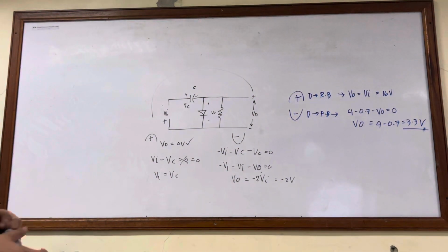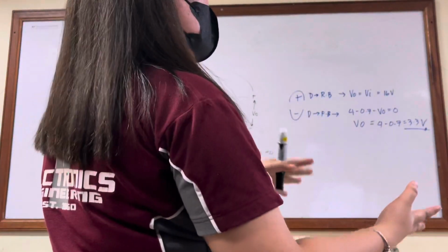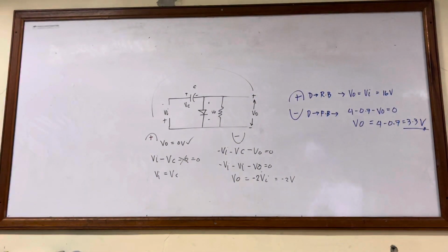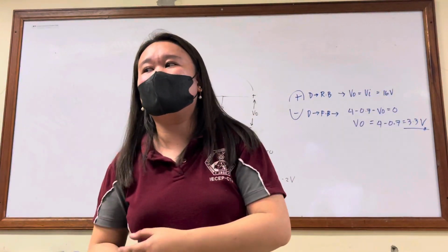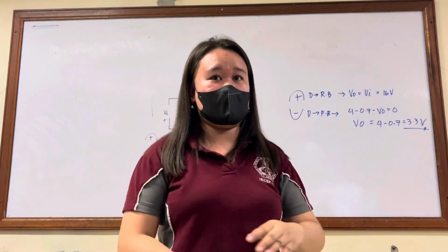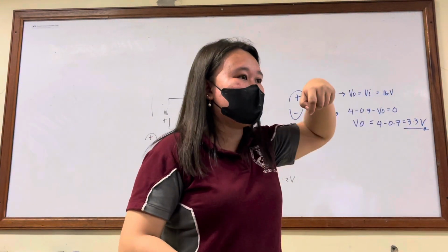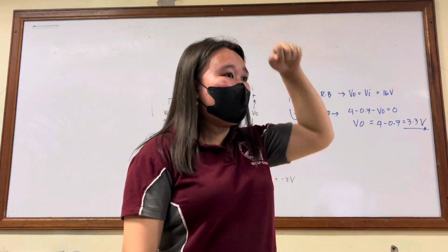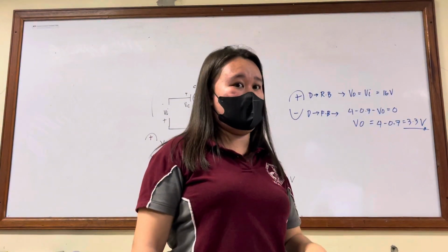Okay. Check that the total swing of the output matches that of the input. I will explain later. The meaning here, class, is that whatever the peak to peak value of our input, your output signal should have the same peak to peak. Why? Because we are not clipping, we are clamping. So you are just pulling your signal downward. If you just pull it, it has the same peak to peak. They only differ in location.